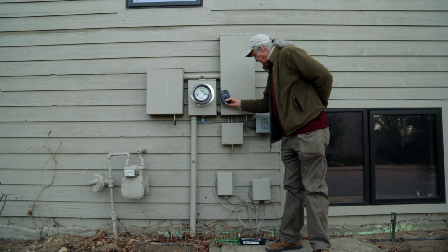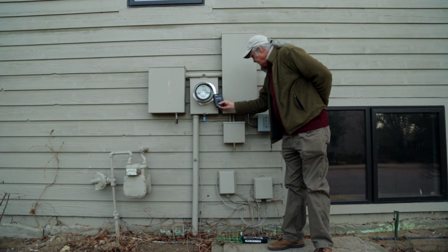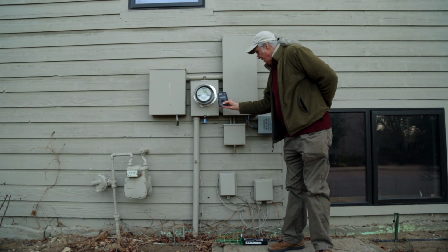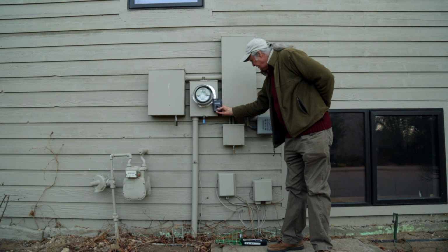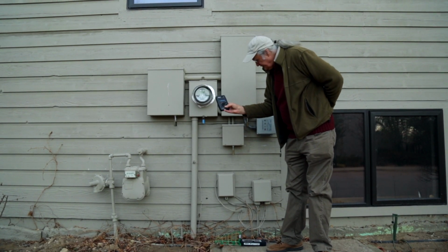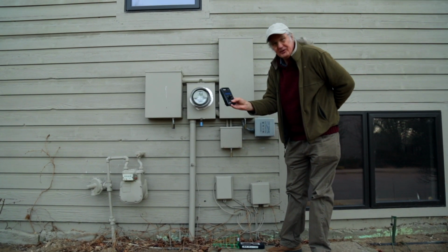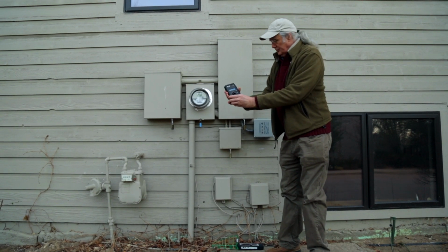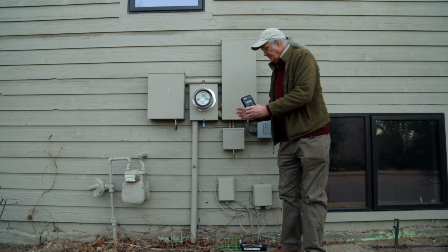And close to these sources we have 9 to 12 milligauss, 19, 20 milligauss here, 40 actually. But even 1 foot away, it's down to 7, from 43 down to 7. And then 2 feet away, it's already down to 2. 3 feet away, it's down to 0.7, which is fine. Anything less than 1 milligauss is good as far as we're concerned. So most of the reduction occurred in the first foot or two.